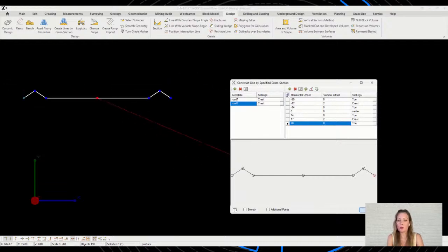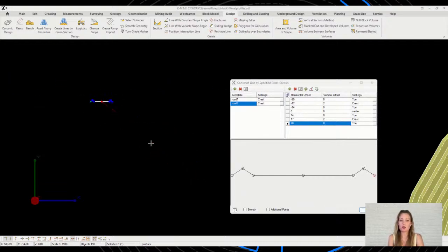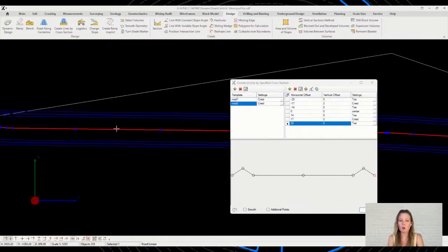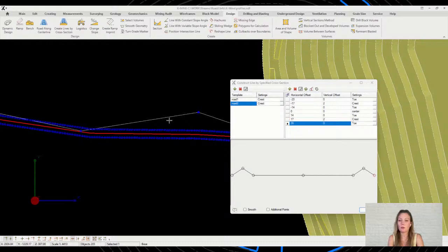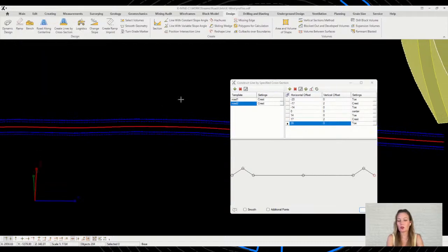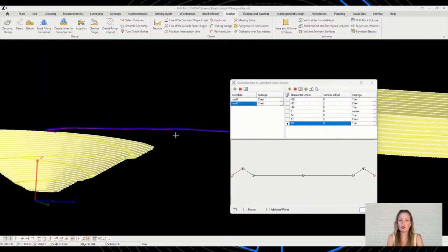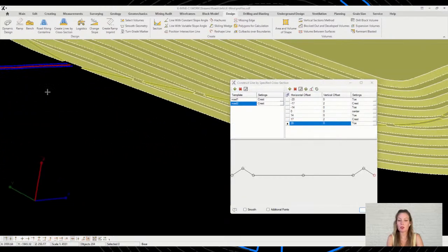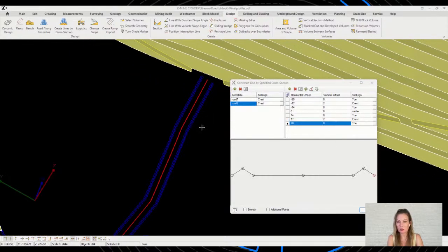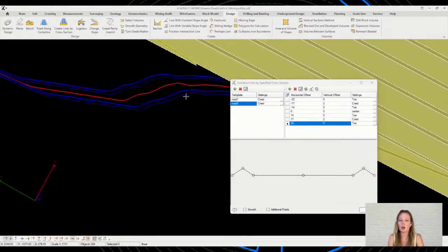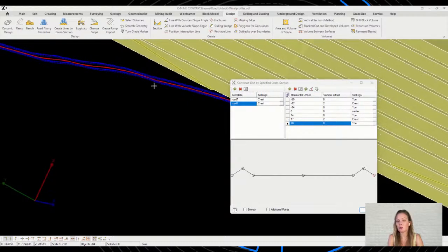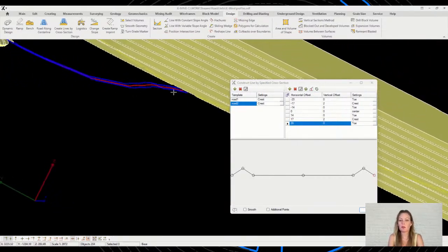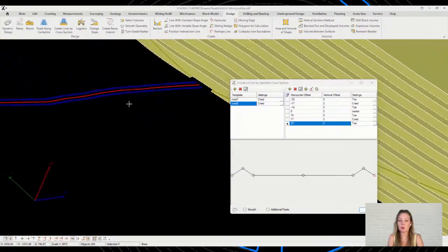So once all the points have been identified, we can distribute the road profile along our center line. With a single click, we'll have a complete road ready to go. In this example, we used a road profile that contains 2 windrows and the roadway itself. Elevations correspond to given coordinates, and that's all. Ideally, of course, you can also build lines on the topography itself relative to the road to complete the picture, but these are already details that will not be difficult for an experienced designer to build.